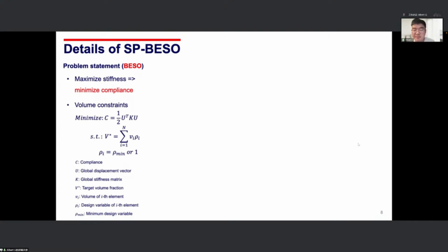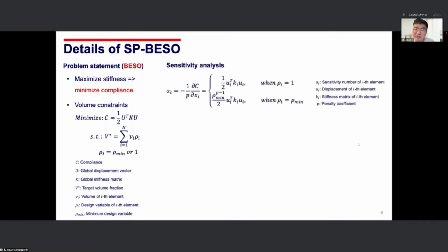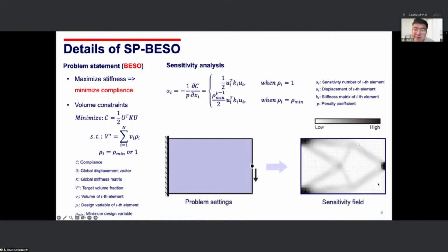Among many steps in the BESO framework, an important part is sensitivity analysis, which can rank the elements according to the results of finite element analysis. The ranked elements can be optimized using the bisection method to create the optimal design. In other words, the sensitivity field represents the consideration of structural performance and decides the formation of a final design. So, if we visualize the elemental sensitivity field with a texture, we can obtain a grayscale image, which will be useful in the following steps.